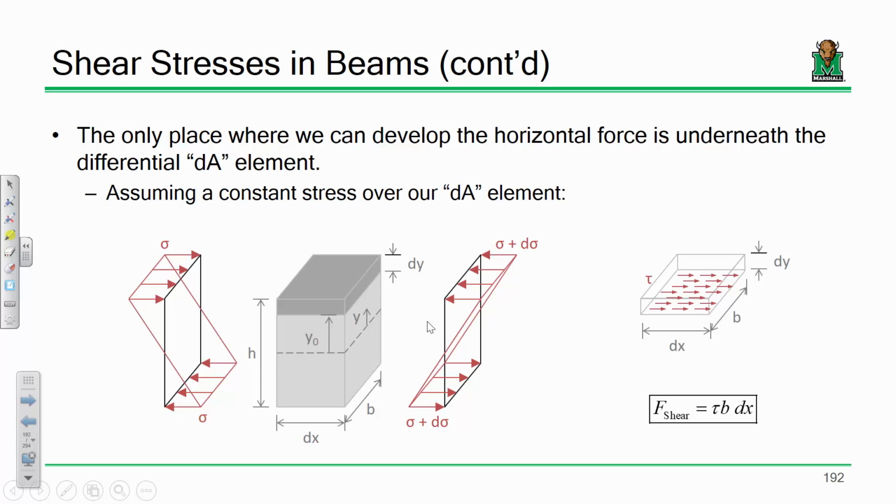It goes back to the book. If I take the book and I bend the book, the pages are sliding across one another. I propose that inside of a beam, inside these layers between the beam, there's a force being developed that's keeping that beam flat. In other words, imagine what happens if I superglued all these pages together. That superglue is going to experience some stress if I bend the page, right? That's what I'm going to try and compute.